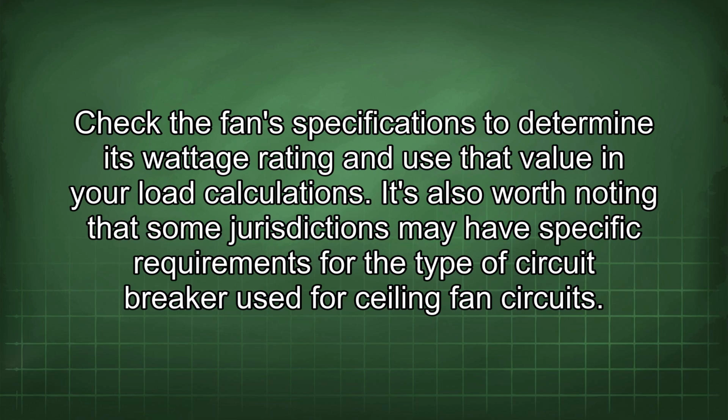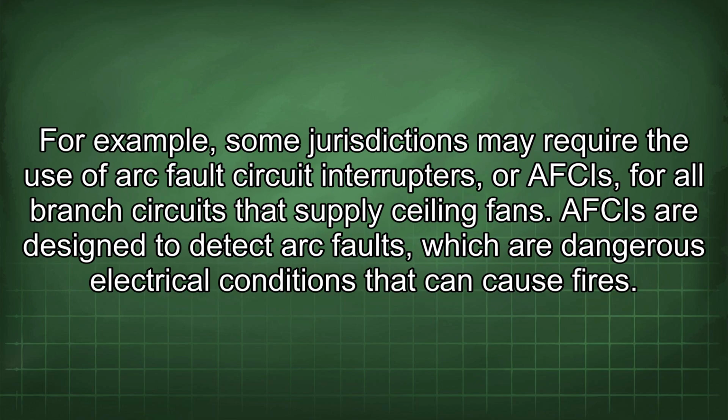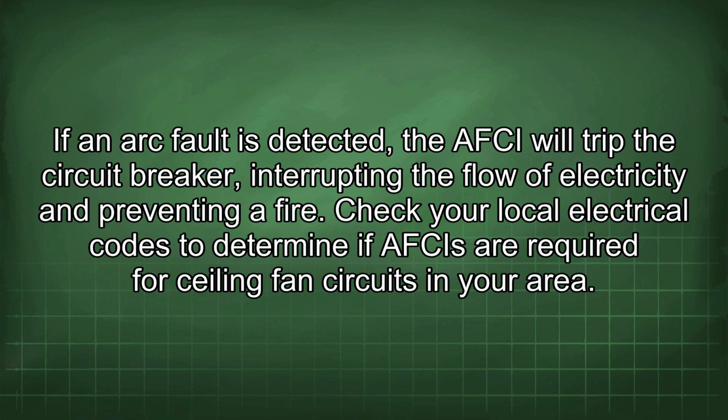ceiling fan circuits. For example, some jurisdictions may require the use of arc fault circuit interrupters, or AFCIs, for all branch circuits that supply ceiling fans. AFCIs are designed to detect arc faults, which are dangerous electrical conditions that can cause fires. If an arc fault is detected, the AFCI will trip the circuit breaker, interrupting the flow of electricity and preventing a fire. Check your local electrical codes to determine if AFCIs are required for ceiling fan circuits in your area.